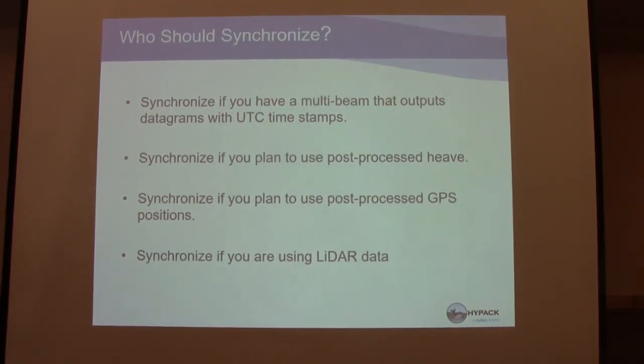But this is something on the computer that you need to make sure is set correctly if you have the hardware in place, and that's PPS. All multi-beam systems, in my opinion, require PPS. You can run multi-beam without PPS, however, it's not going to be that accurate. You don't want to use a straight ZDA message for time tagging for multi-beam data. You want to use a pulse per second signal.